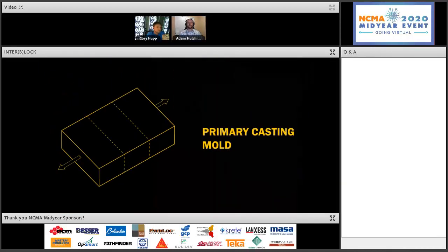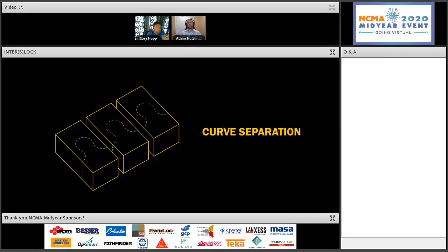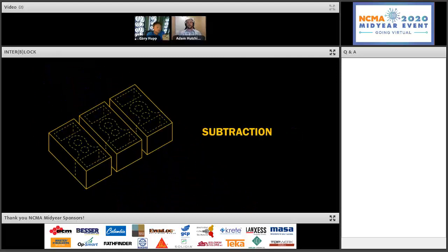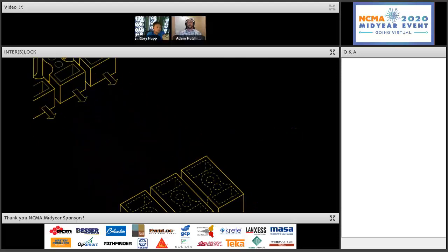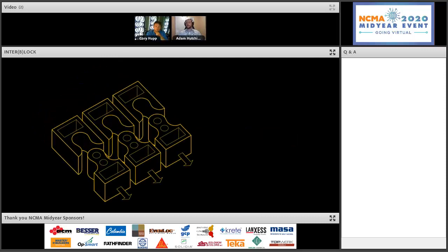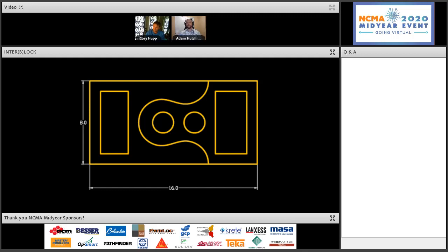Interblock fits 6 modules into a mold box, producing twice the number of blocks and utilizing twice as much concrete compared to a standard CMU. Fitting within the mold box allows for simple tooling and seamless production integration, enabling swift and scaled manufacturing of these modules. These are the dimensions of 2 modules interlocked together.